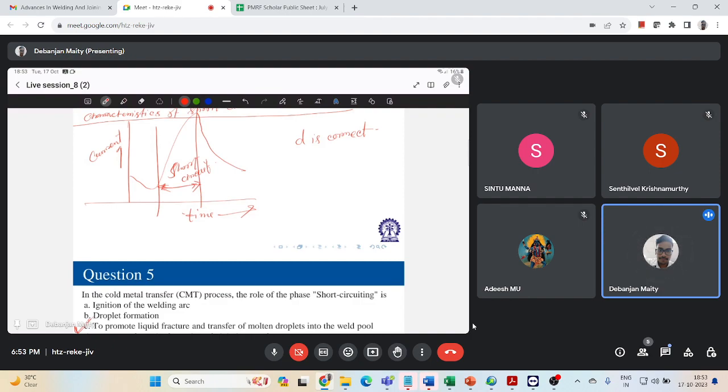So those things are there. Now, instead of laser as a source, you can think about electron beam as a source. So at that point of time, it will all be electron beam melting, right? In both the methods, the energy is used to melt the materials and bond them together. In one case you are using laser as a heat source, and in the other case you are using the electron beam as another heat source, right?